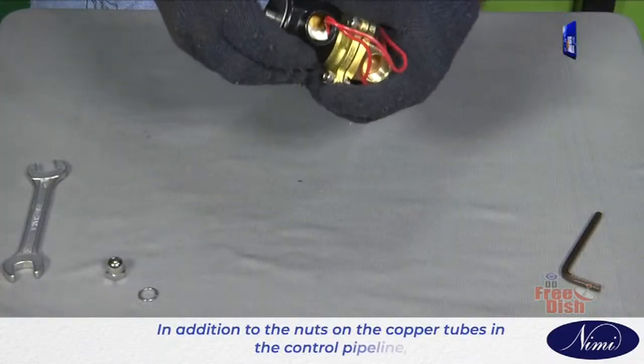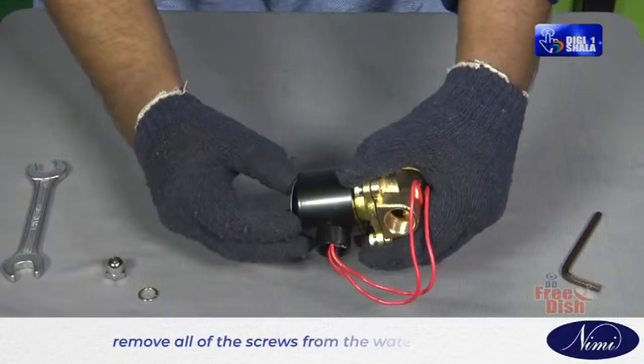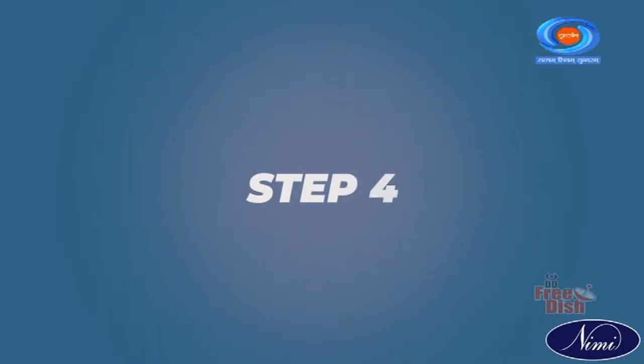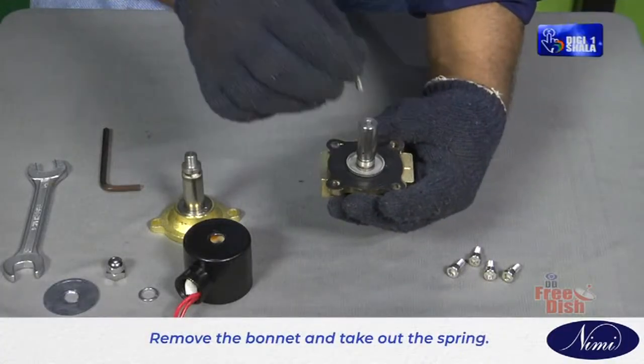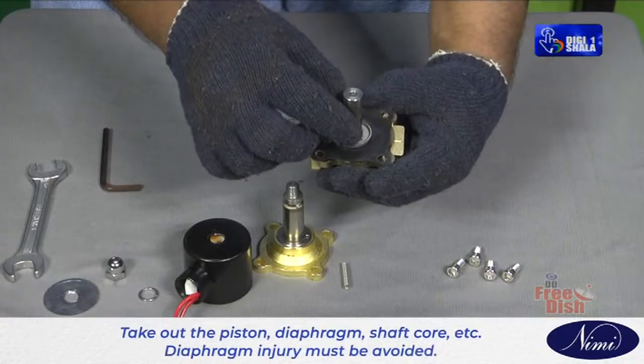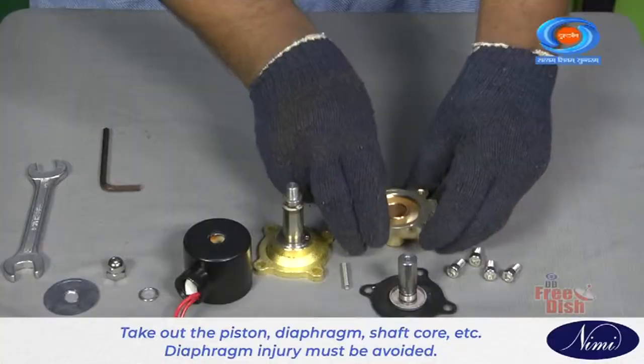Step 3. In addition to the nuts on the copper tubes in the control pipeline, remove all of the screws from the water solenoid valve. Step 4. Remove the bonnet and take out the spring. Step 5. Take out the piston, diaphragm, shaft core, etc. Diaphragm injury must be avoided.